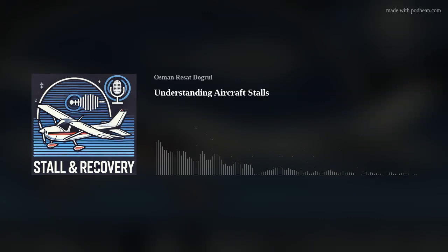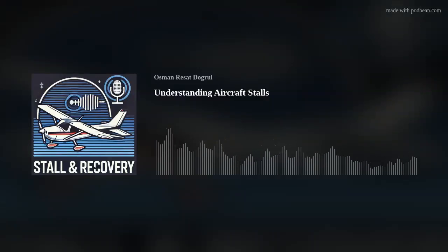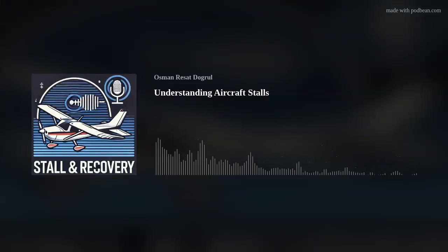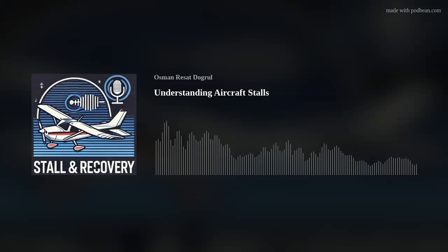Superstall characteristics. Nose-up pitching tendency: at stall speed, the aerodynamic center moves forward, increasing the nose-up effect. Wingtips stall first due to higher loading, shifting lift distribution forward. Forward fuselage lift increases, worsening pitch-up tendencies. Ineffective tailplane: as the aircraft stalls, the disturbed airflow from the wings reaches the high-mounted tailplane, reducing its effectiveness. Without clean airflow, the tailplane cannot provide the necessary nose-down pitch to recover.